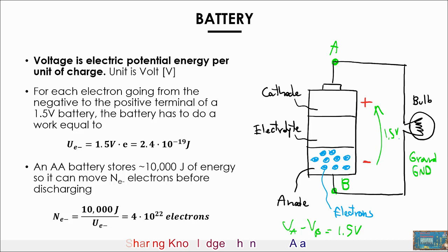And most of the time the circuits will also have a special symbol to indicate this node, and this symbol could look something like this, like a triangle hanging from a wire, or something like this. These symbols imply that that node is physically connected to the earth, to the ground under your house, for example. The reality is that it's not true most of the time. Think about a mobile phone. It's definitely not connected to anything. It is a standalone device. But the symbol is used nonetheless to indicate that that node is considered to be at 0 volt.